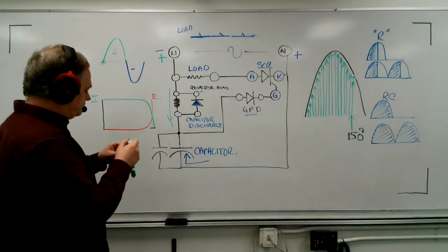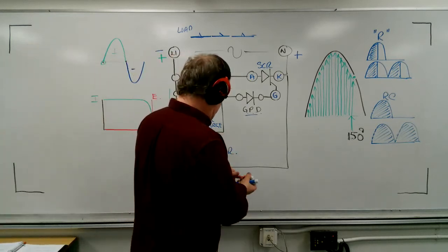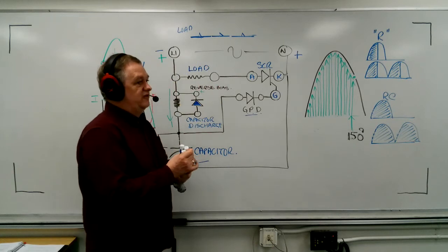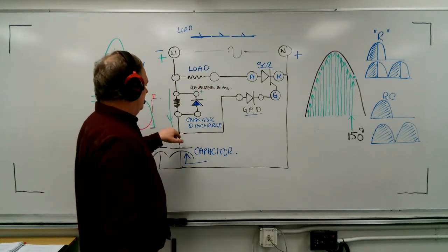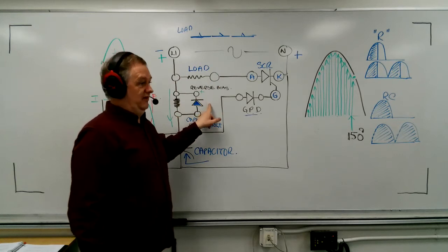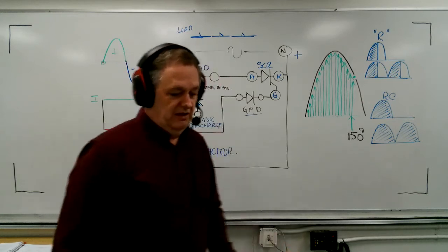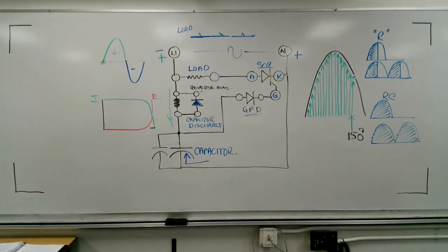And like I said, several different capacitors are used in different circuits. So this one's very important that it is connected reverse biased. So if you go and you connect this up the other way, definitely going to have a circuit problem.